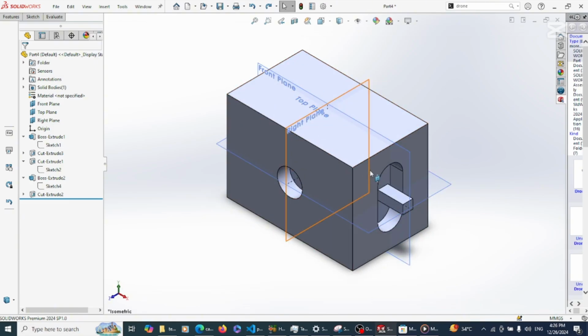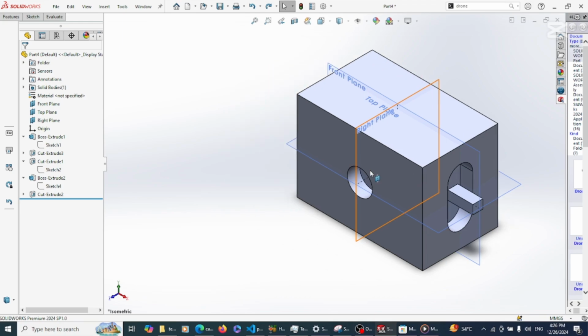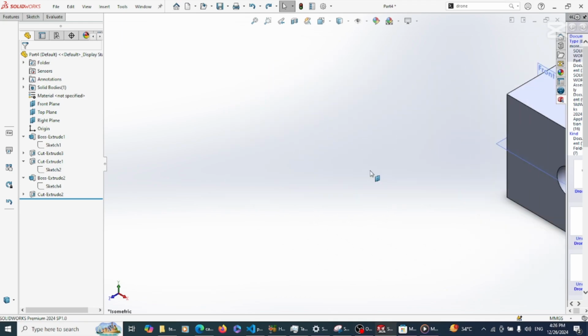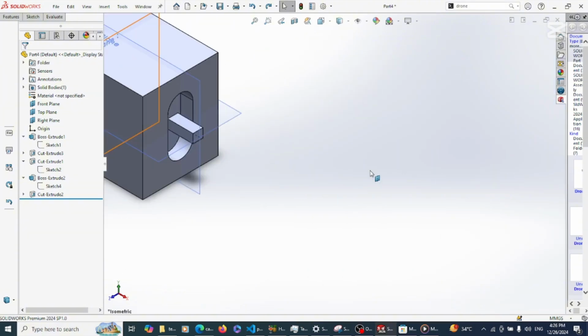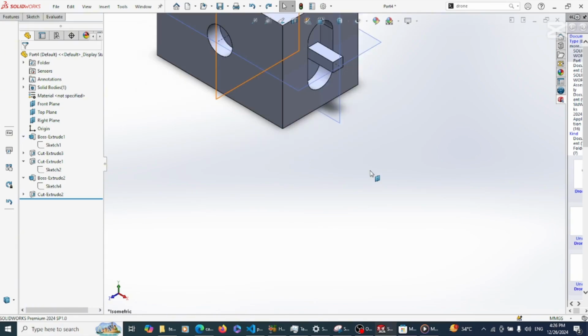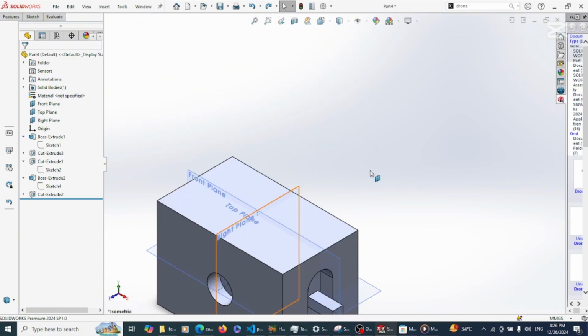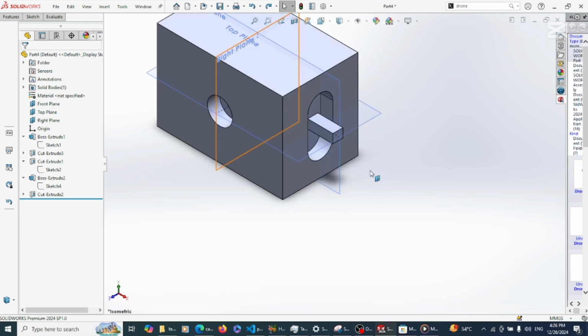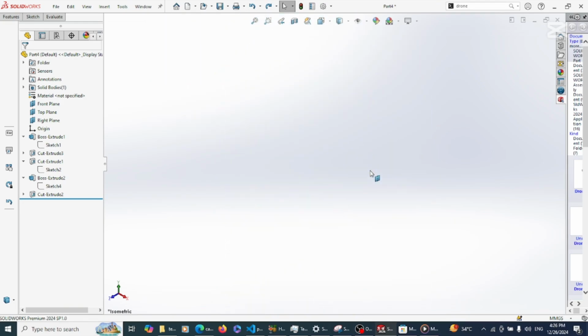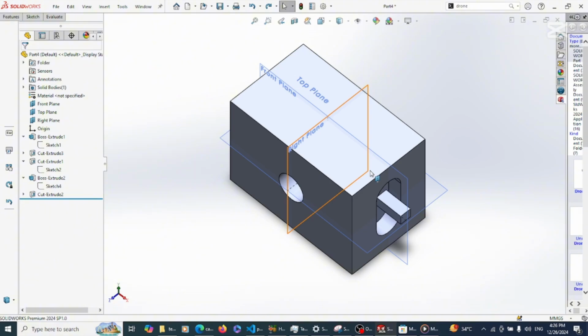Now, assuming you want to pan, the way this guy is now, I want to move to the side, just the way it is. I hold Control and I'm using my right arrow key on my keyboard. Direction keys on my keyboard. So it's moving. I'm moving it left now, using the left key, moving it upward with the up key, and down arrow key. I'm still holding Control. So you hold Control and use one of the arrow keys to move. So assuming I lost this guy, I can just press the key F, simply just the key F, without pressing any other thing. F, it brings it back to perspective.